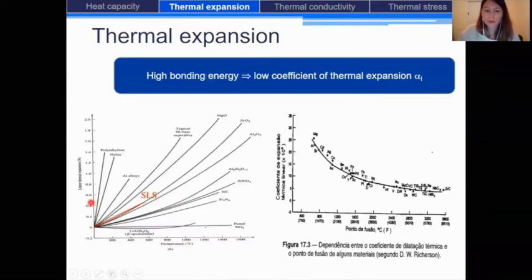In this graphic we also represent the value for linear thermal expansion as a function of the temperature. And as you can see, in the case of polymers, for example polyethylene and nylon, the linear thermal expansion will be much higher for a small value of temperature, whereas we have intermediate values for alloys and for some ceramics, and for other ceramics like fused silica we have almost no thermal expansion of this material up to very high temperature.